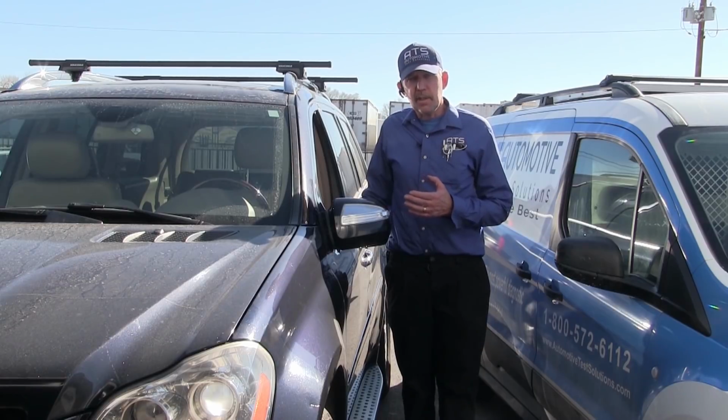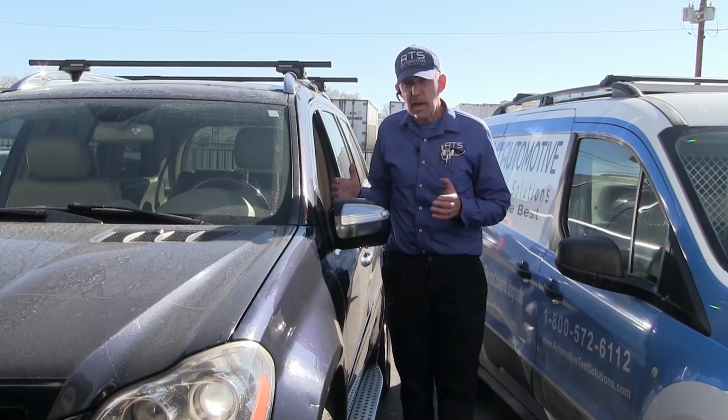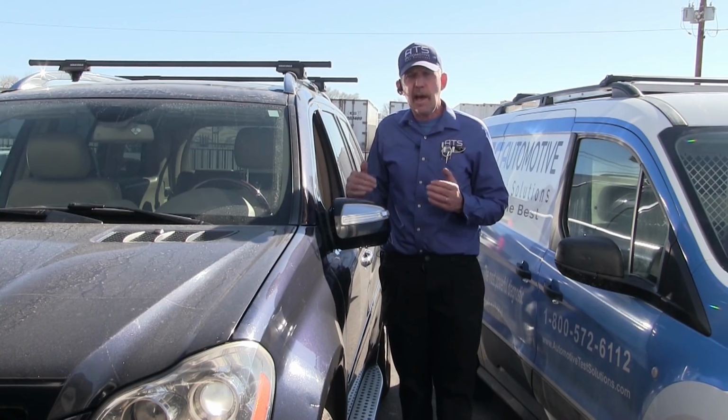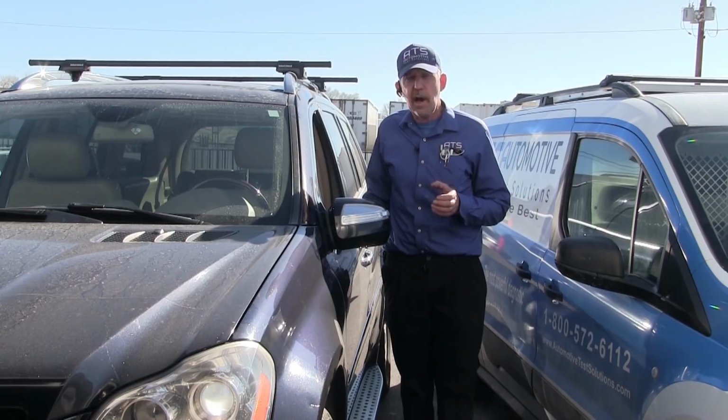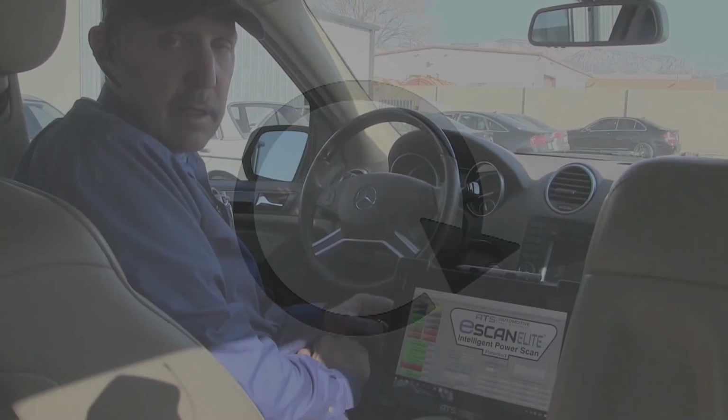The fuel pump in this vehicle, the whole assembly, has already been replaced with a factory fuel pump and it's still running lean. So now our job is to find out what's really wrong with this car and diagnose it correctly. The first thing I want to do is get a scan tool in this car and go for a test drive and gather some basic data so we know how to diagnose this car when we get back over here. So let's jump in the car and go for a test drive.